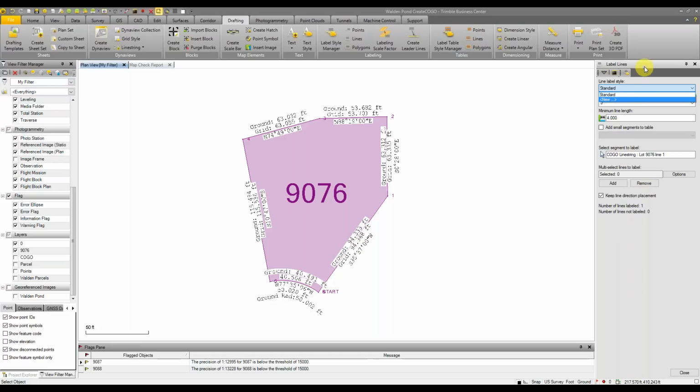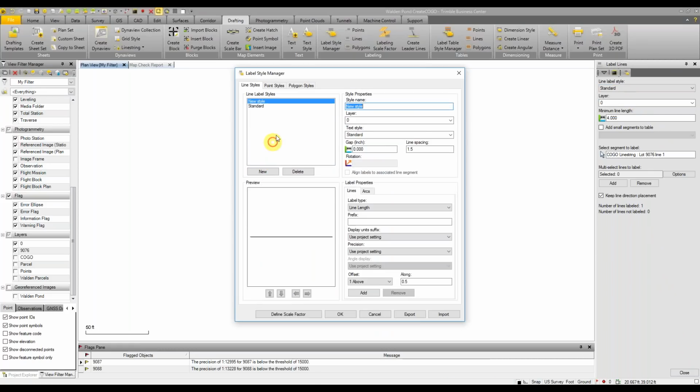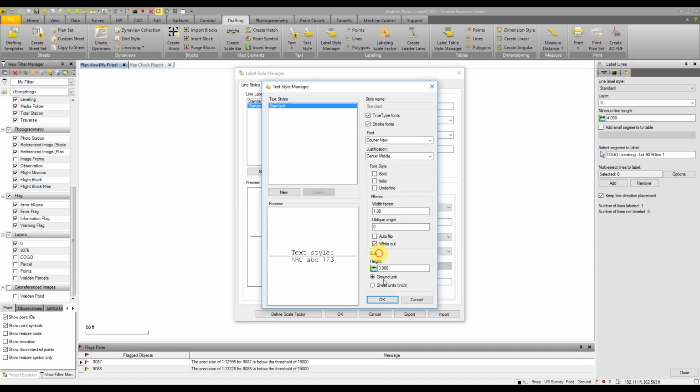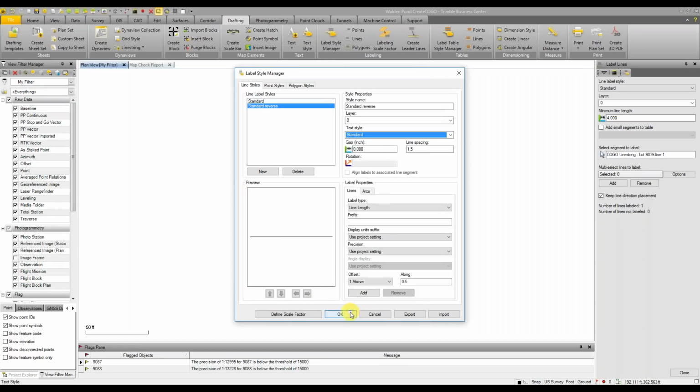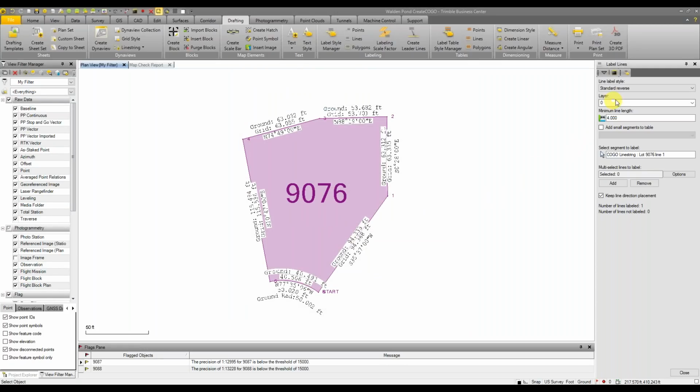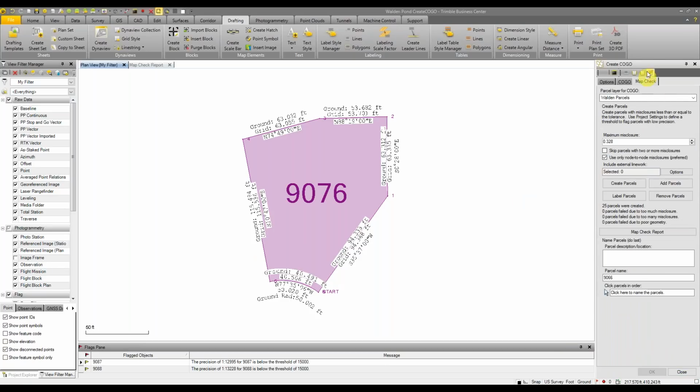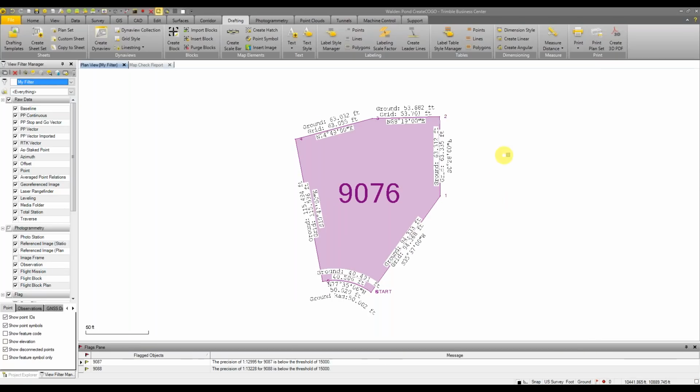Troy may want to address that. So the scale factor for labeling can be a different value than that for your entire project. Usually the local site settings establishes a project-wide scale factor, but in the vicinity of your COGO work there, you can choose a different scale factor so that the labeling is local to that part of it. So it's just like having two different scale factors allows more flexibility.